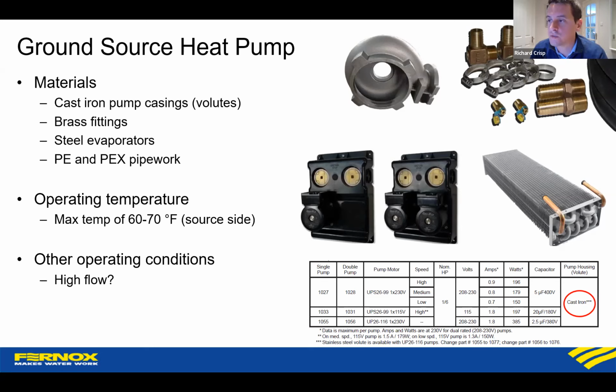It's one thing to protect a system against failure. It's another to keep it pristine enough to get that efficiency, which is why heat pumps are becoming more and more popular across the world. It's getting that COP of 4 rather than trying to pump around sludge and not getting that efficiency.